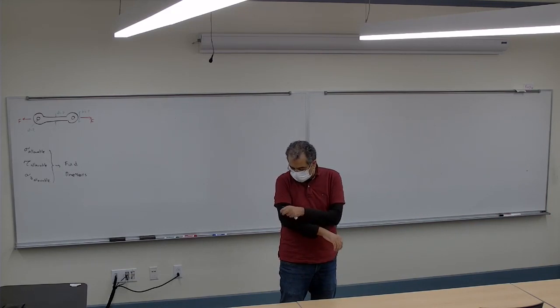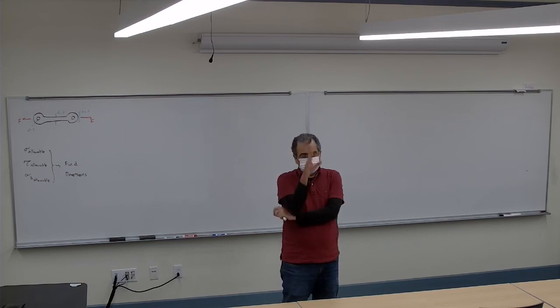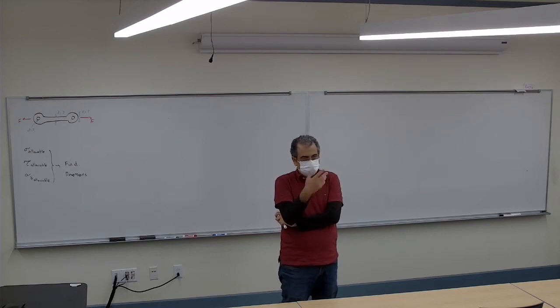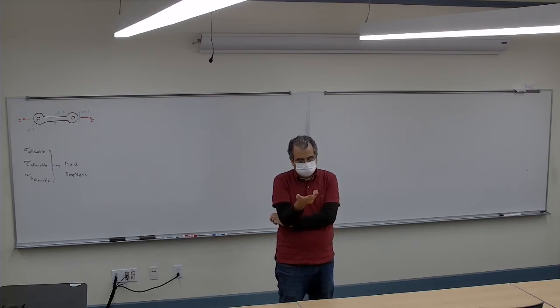That also happens a lot, especially when you design something. I've seen it a lot. For example, you put a very specific type of welding there, and whoever does the welding decides that his experience is more than your knowledge. If you ask for 20 centimeters of welding, they say, no, I think 15 centimeters is enough. They just don't do it. So all these things may happen and will happen when you design.